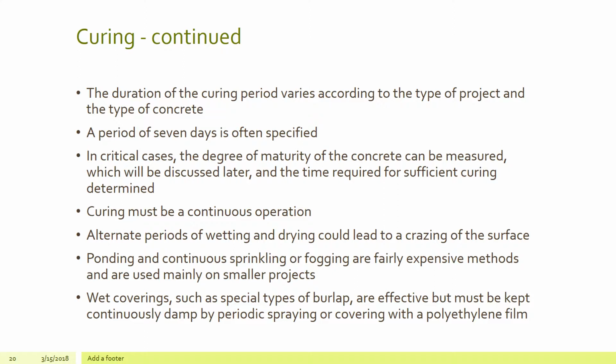In critical cases, the degree of maturity of the concrete can be measured, which will be discussed later, and the time required for sufficient curing determined. Curing must be a continuous operation. Alternate periods of wetting and drying could lead to crazing of the surface.